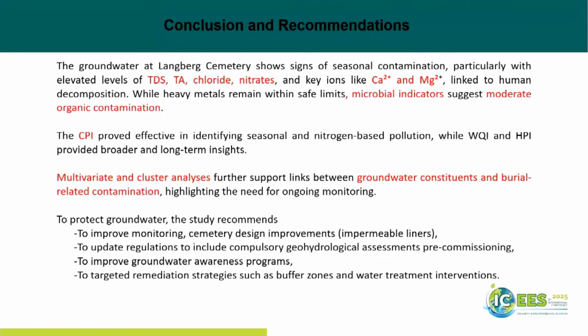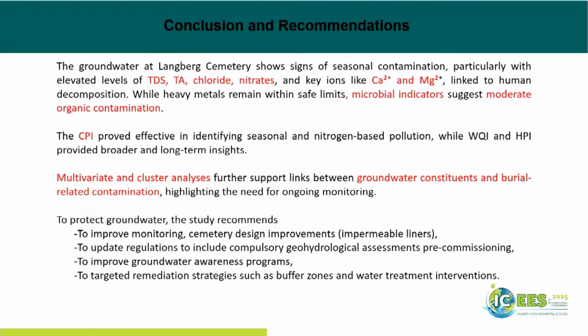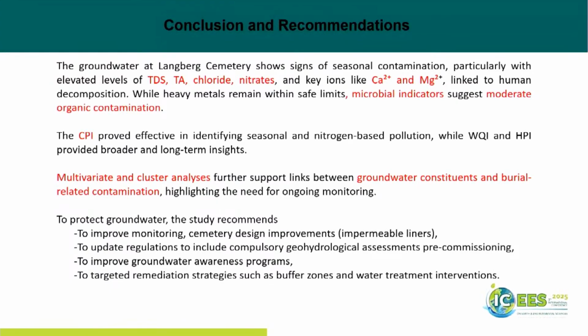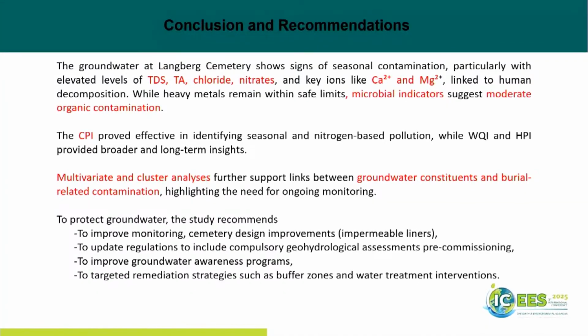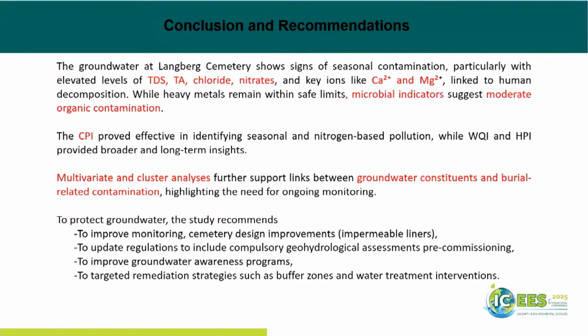So what is our conclusion? We are concluding from this study that was carried out during a period of 5 months, that some of the pollution is a result of the presence of the physicochemical parameters such as TDS, total hardness, chloride, nitrate, while ions such as calcium and magnesium are the ones that are caused from the human decomposition.